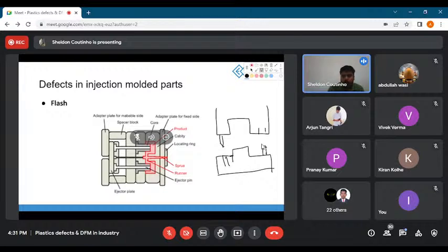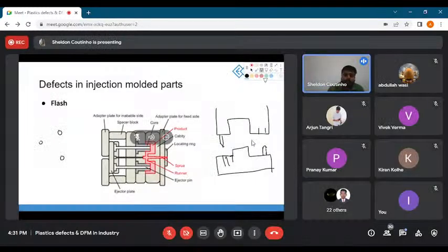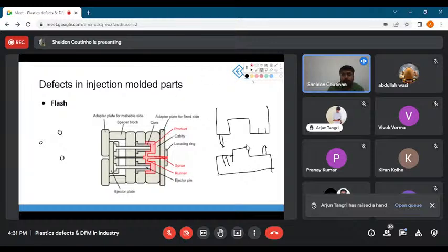And a rule of thumb is, you want to arrange them in a pattern. Like, this is the side view. On the left, I'm drawing the top view. So you want to arrange it in a pattern of a triangle or something like that, so that you don't have any chances of twisting or something like that, which rarely happens. But just in case, to prevent that, you can also arrange it in a triangular pattern, to understand in which orientation these things fit as well. So this is how you can prevent the mismatch, because they'll be properly designed to fit into each other.